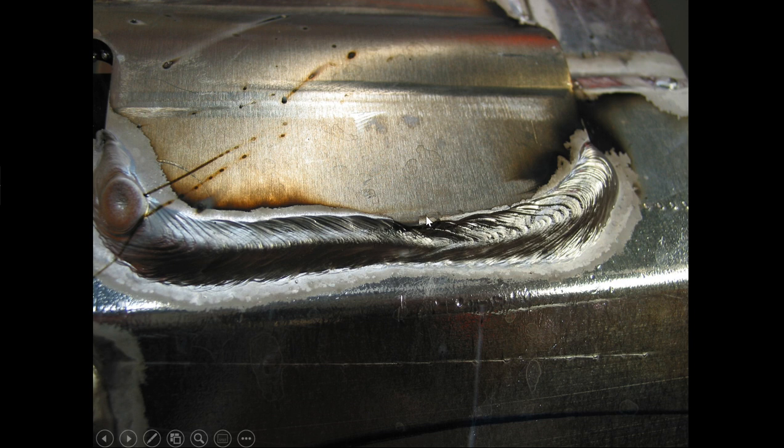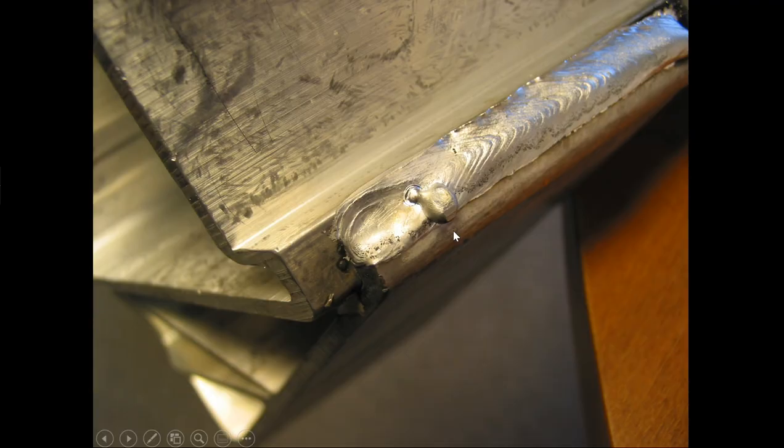It very well could be binding the wire in such a way that just holds the wire back. And if the wire is being held back, it just makes the wire a little bit starved. And then it changes position, it loosens up, and then it welds normally again. So watch out for things like this. It could also be just because the contact tip is starting to die, and it started to stick a little bit, and then it cleaned itself up.